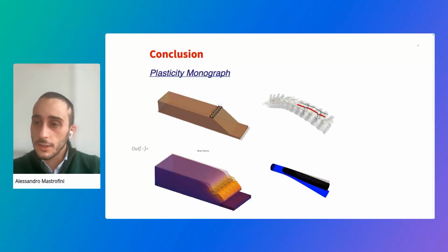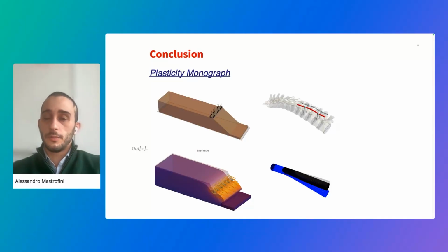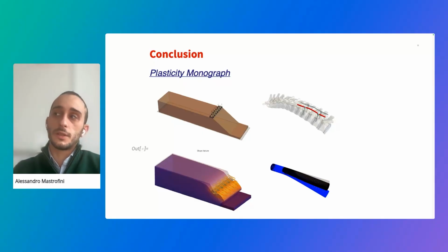Rather than specify an iteration limit, is it possible to prescribe a convergence criterion? An iteration limit alone may not guarantee a converged solution. Yes, of course, this is possible. We have different criteria implemented, but you can set that. You can also set another condition manually by evaluating the difference between the displacement and the displacement at the previous step. You can also evaluate in stress, but of course you can set it.